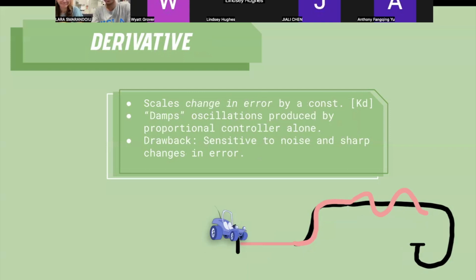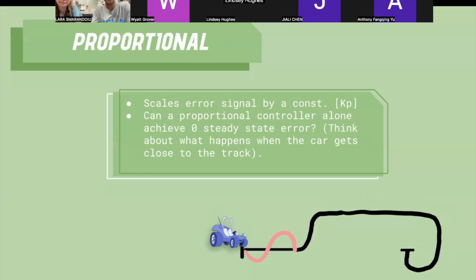So when we say you scale your error, right? That doesn't necessarily mean that you exactly take how much distance you are and then translate that. You need to map it to some value, right? For example, to make this more concrete, you can make your car move slightly to the right, say 1 inch per second, right?